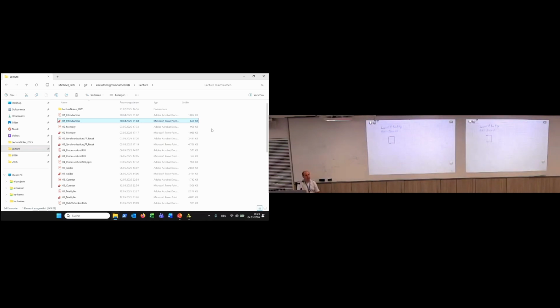On this area, you define an I/O ring, or besides this area. So we have a specific part. You have corner cells where nothing happens, and then you have something like pads, usually with a little bit of space in between, which gives you effectively the I/O ring. Why is this needed?